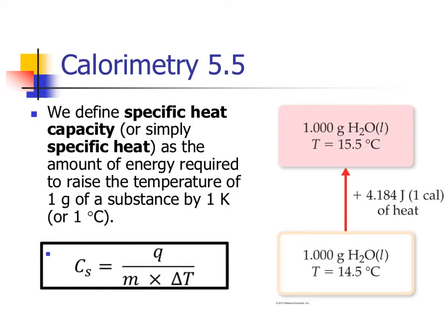As we look at, again, specific heat, you can calculate it out. I'm not a big fan of this equation. I usually like it spread out into the values where you're actually calculating Q or heat. For that, you will find specific heat written in a couple of different ways, and that is C sub s. M is for mass, that's pretty common, and a delta T for your change in temperature, so your final minus your initial, as always.